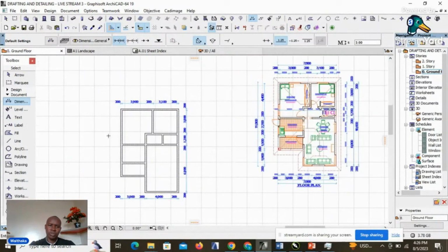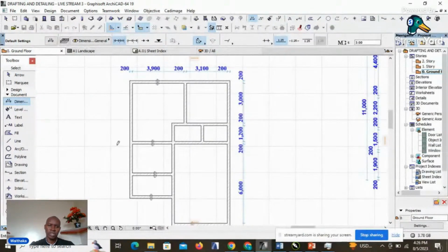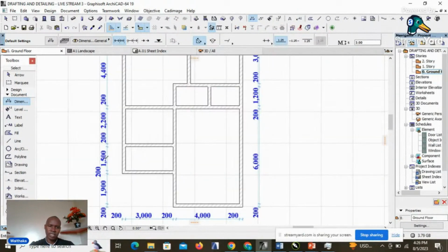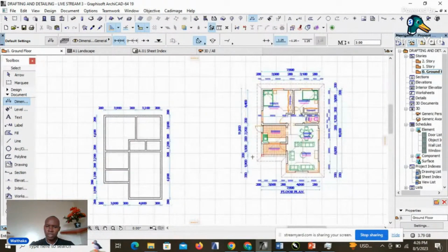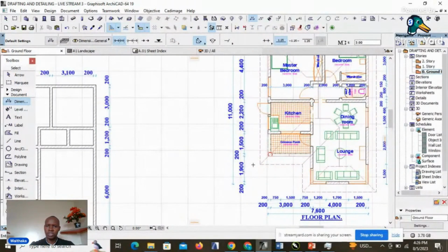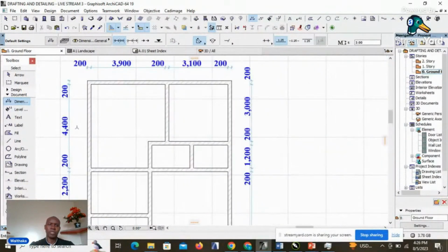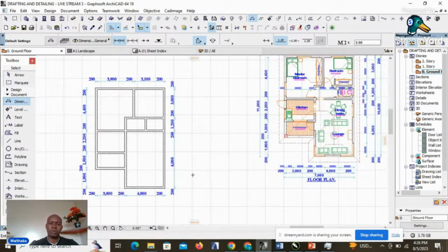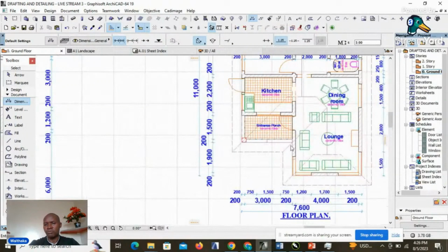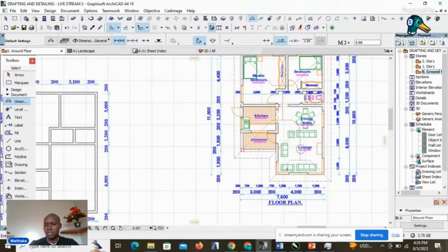Then we do the same on this other side just to confirm and see whether we have the dimensions as required. So you step on all the walls that you want to insert dimensions on. Then on this side you double click and then you click again, and that will give us 1900, 15, 22. This is 19, 15, 22, and again 44. And therefore we are sure now that our walls are aligned as we have been given in this design.